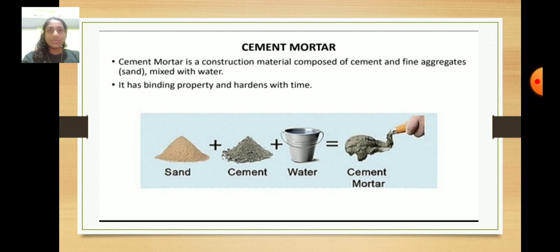To prepare cement mortar, cement and sand are properly mixed in dry condition. Water is then added gradually and mixed using a shovel. The water should be free from clay and other impurities. Cement mortar can either be mixed manually, hand mixing, or mechanically, machine mixing.